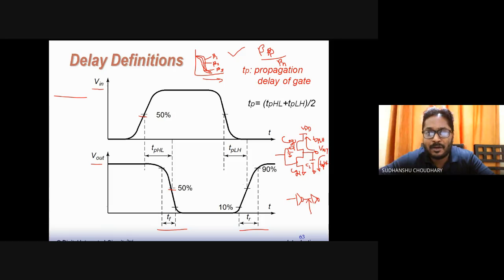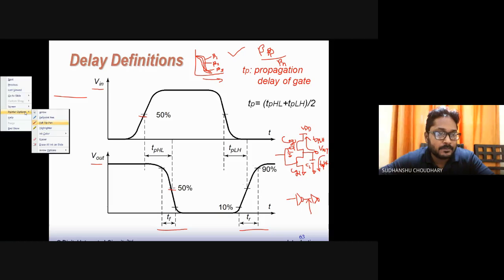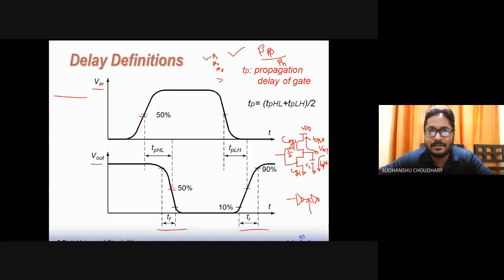Currently, I think you might be plotting a symmetrical VTC. There are cases when the pull-up and pull-down network resistances are not equal. Then the VTC will also not be symmetrical. So the VTC will change if the pull-up and pull-down resistances are not the same for the MOSFETs, and you will see a non-symmetrical VTC instead of a symmetrical one. Anyhow, these issues we will talk about later, as they are a part of this course.